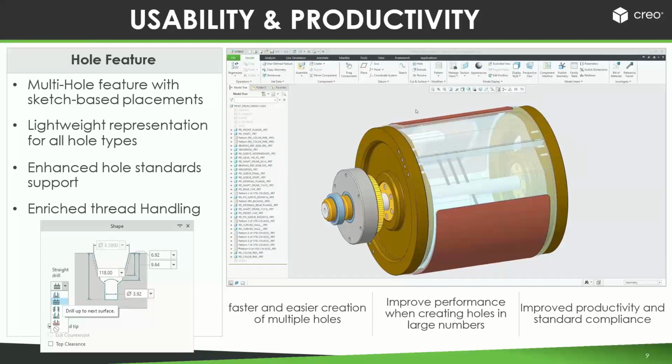All right, with Creo 8, we've also added enhancements to our hole creation capability. We've added the ability to create multiple holes within a single hole feature. This is based upon a sketch. So the user will create a sketch on a particular plane. And if they have points that are defined in that sketch or endpoints of linear entities, or even midpoints of linear entities, a hole will be created at that location. Allows you to create many holes within one single hole feature. That's simplifying the overall process. It's speeding up regeneration time, and also reducing the size of the model tree.